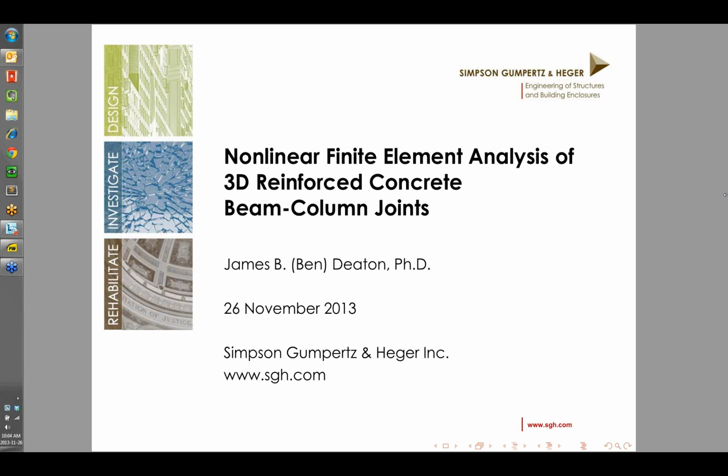And the nice thing about the FEA is that once we've built the model, we can easily vary these different parameters. Like for instance, if we are designing an FRP retrofit, we can analyze a joint using a tool like this, and then we can test 5 different retrofit or rehabilitation measures that we could never do in the lab. So I think it's highly cost effective with respect to experiments, but the catch is that, as I'm sure you know, we have to have valid experimental data for a similar problem that we can use to validate our model, so that we can be confident that